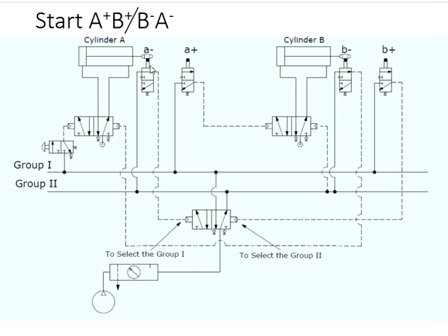That means the limit switch connection should be given in the actuated mode. That means this is a 3/2 valve which is roller actuated. The default connection is the lower portion, so you have to give a compressor line to the lower portion. When this roller is actuated, the top one is activated.